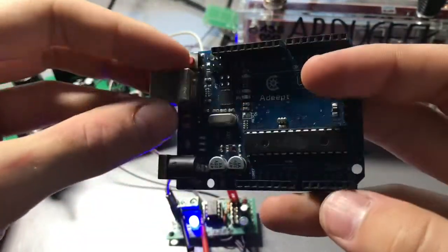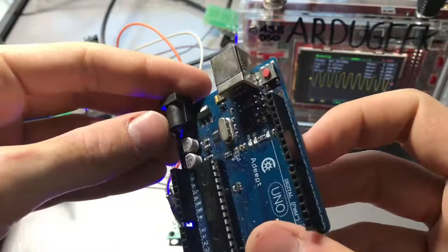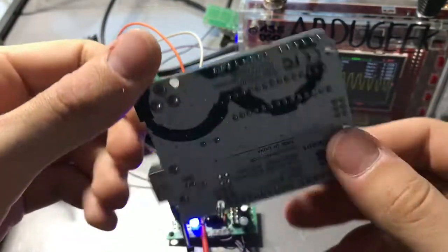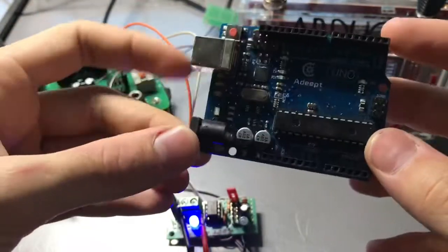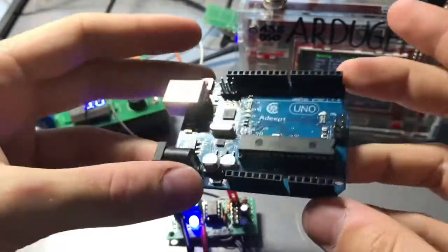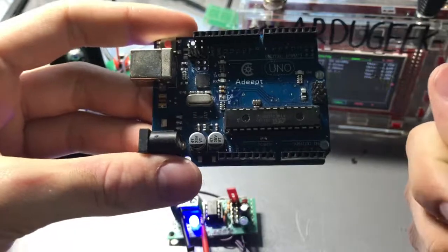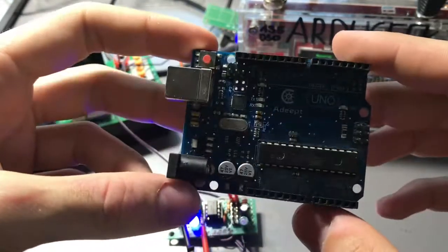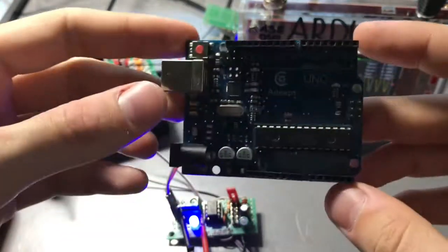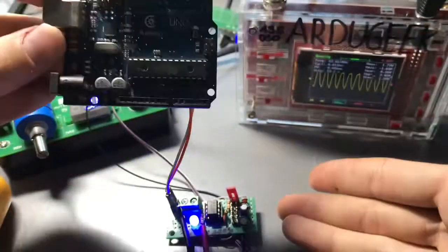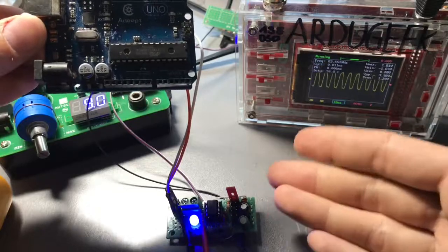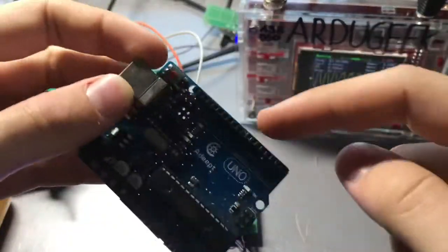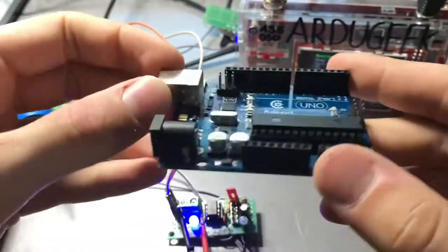has 13 digital pins and 5 analog inputs. So it is just too much. Sometimes you just want to turn on something, turn off, or just make a simple flip-flop or something like that. So sometimes it is just easier to do it in an analog, old-fashioned way with a 555 timer instead of programming a whole Arduino Uno and wasting all the other 10 pins or something like that.